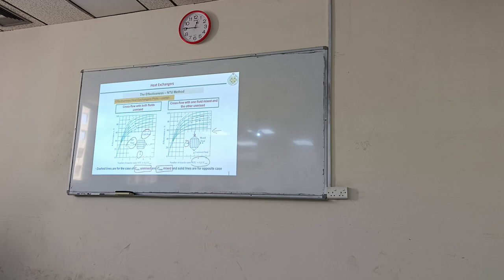For both unmixed, there is only one single line, but here you have two options: which fluid is unmixed and which is mixed, the minimum one or the maximum one? Those equations are also presented in the form of charts.